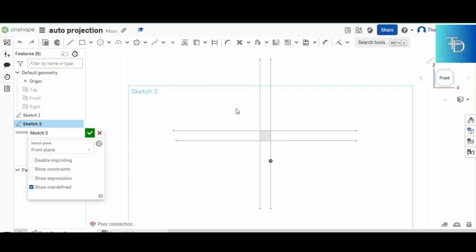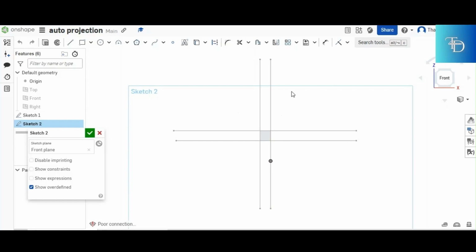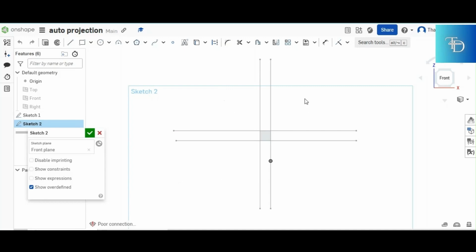Let's try and map where we're gonna put our views. This thing is in first angle, right? So we're gonna have two views at the top and a single view at the bottom. By that I mean we're gonna have a front right there on the first quadrant, and then on the second quadrant you're gonna have the what? The left view. Obviously the front distributes for the left, and it also distributes for what? For the top. So the front is here, at the bottom side we have the top view, and on the right hand side you have the left view, because this thing is in first angle.